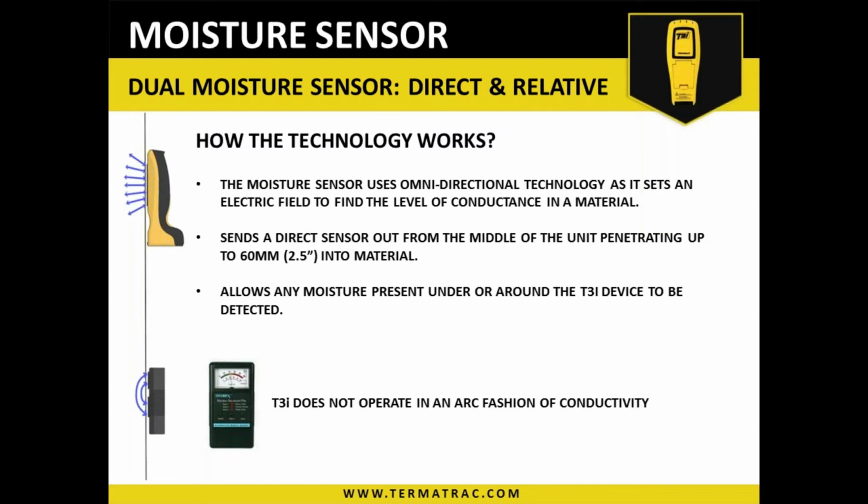Now, all non-invasive meters that fall in this category, the dielectric category, we're not actually relaying the moisture content. They are actually detecting changes in density of the material, which then the units are set up internally with their componentry to move the needle to give us an indicative percentage of that moisture content. So it's not water itself we're actually measuring. We're measuring the density changes, which can indicate that there is a moisture situation in there. So we do need to understand that.